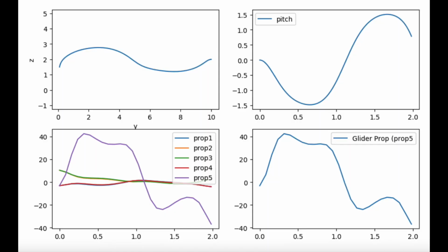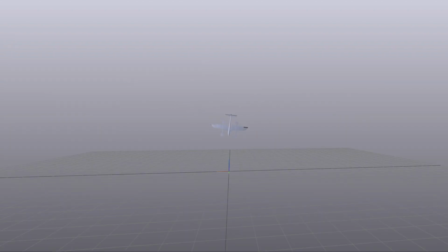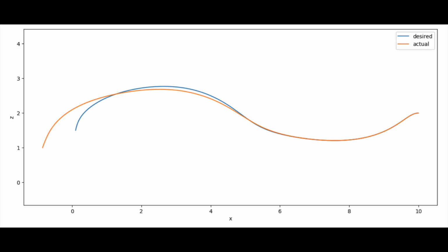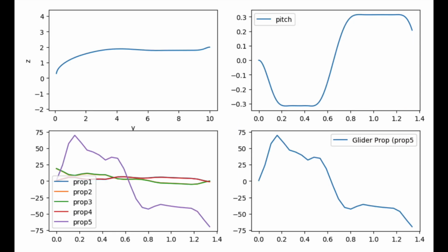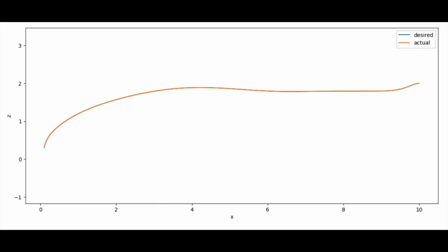The success of this change allowed us to create tighter final position constraints while still being able to find a solution where we otherwise would have failed. While this trajectory diverges slightly more than the first, we can still do better by adding additional constraints. Upon adding constraints on the orientation of the drone, we were able to produce smooth trajectories which don't exploit any complex maneuvers to reach the endpoint. In this trajectory, it's clear to see the successful navigation of the drone with reasonable pitch. An additional benefit of this restriction is the very high degree of accuracy we received from open-loop control.